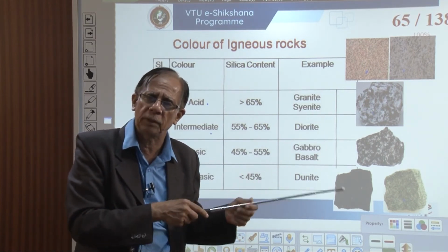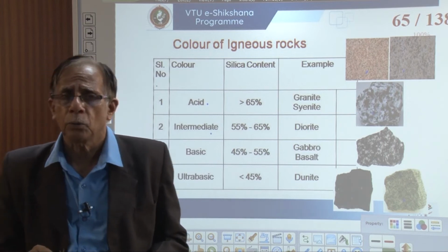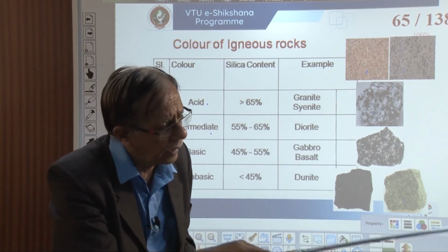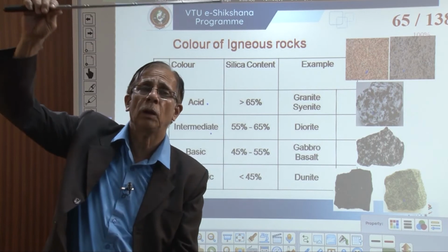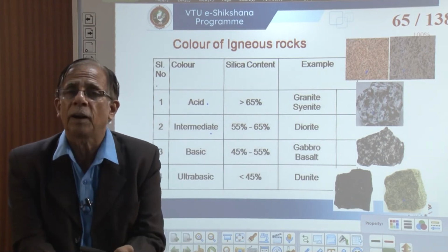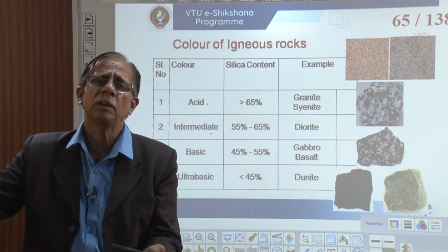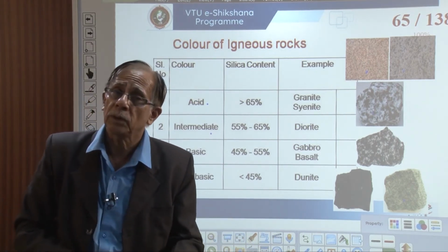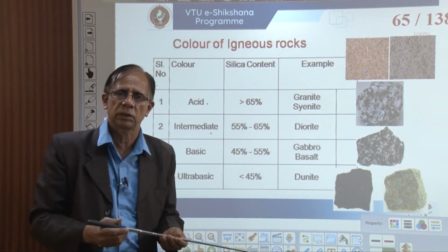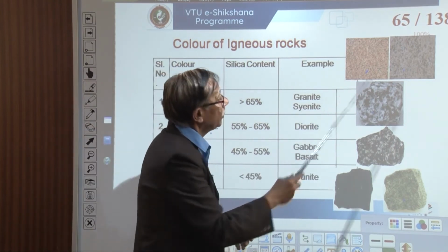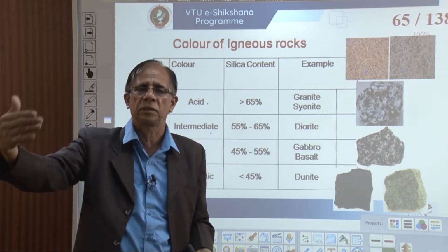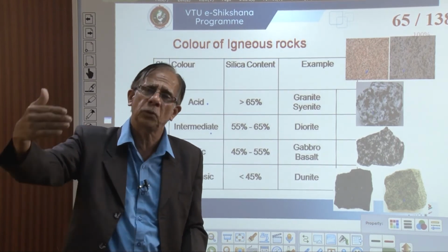Rock looks attractive pink, but to carve Gomateshwara at Shravanabelagola, I wanted that to be placed in air, and it has to withstand thousands of years of atmospheric effect. Between the feldspar and quartz, I find quartz is more resistant than the feldspar. Why is feldspar less resistant compared to quartz? We will discuss a little later, tomorrow, the next session. Because feldspar is sensitive to some kinds of weathering conditions, I prefer those which are rich in quartz.